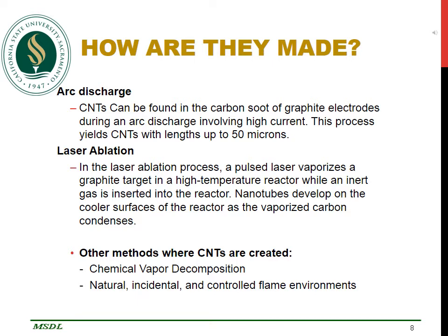Laser ablation is the process in which a pulsed laser vaporizes a graphite target in a high temperature reactor while an inert gas is inserted into the reactor. The nanotubes develop on the cooler surface of the reactor as the vaporized carbon condenses.